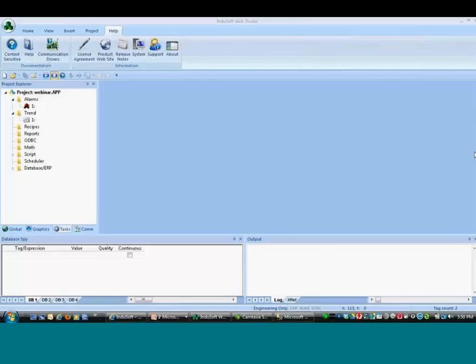How many tags were used for the farm automation project? For that automation project was not very many. It was about 1,800 tags, and that's controlling approximately 20 augers. And I used the class. I could create a class called auger, so that buried inside of each tag I had all the same type of information. And with all those classes and all the augers, it came out to around 17 or 1,800 tags.